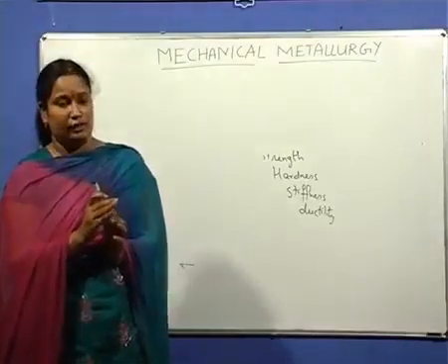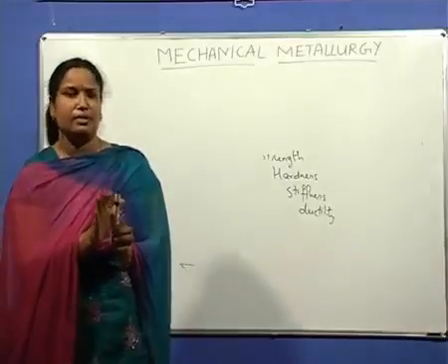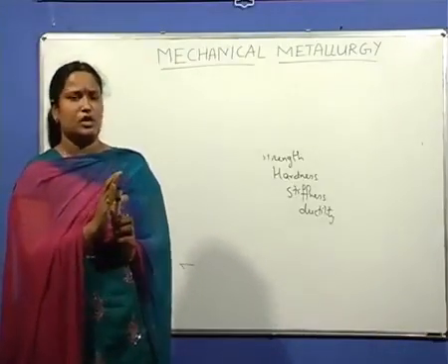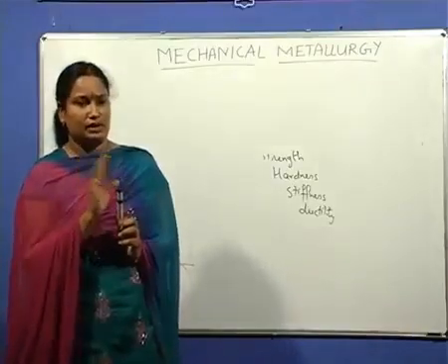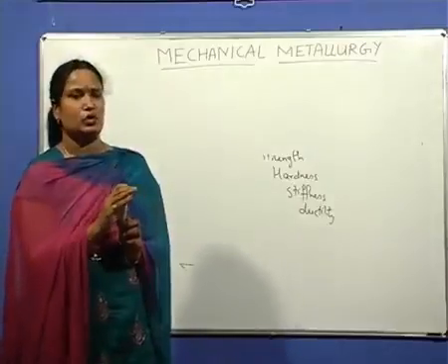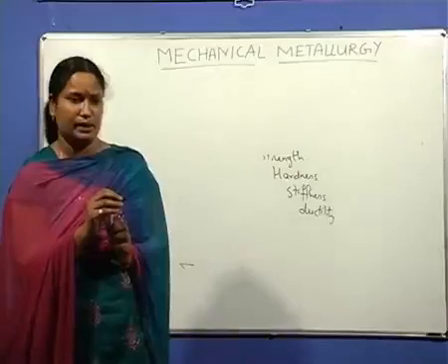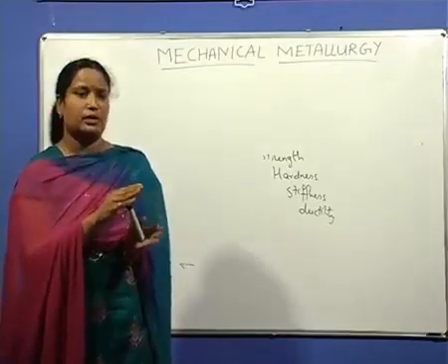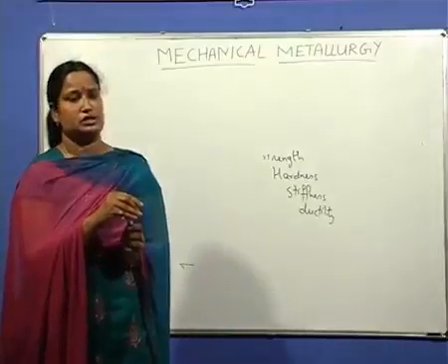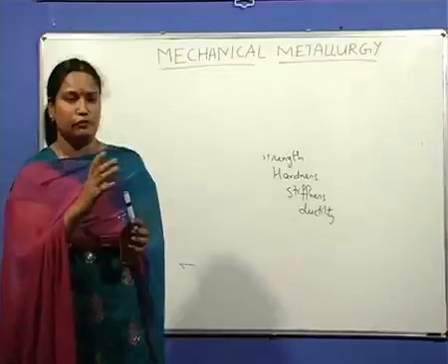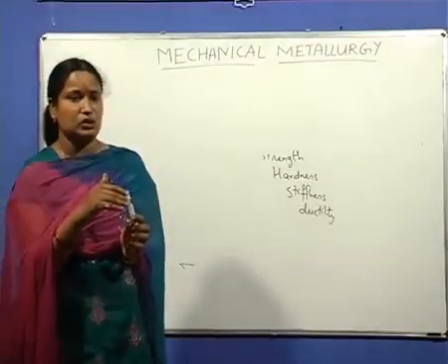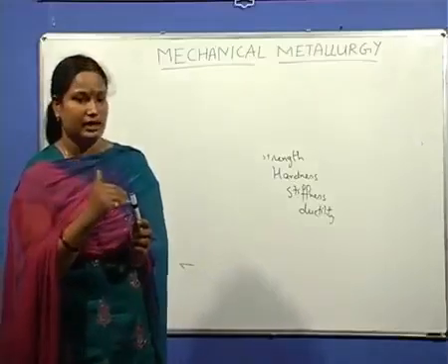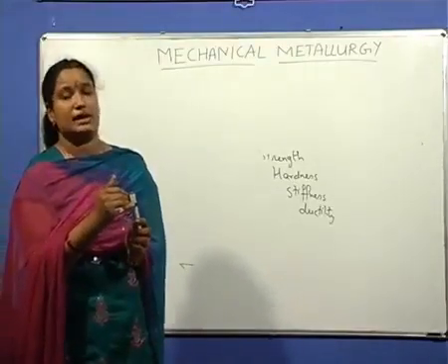The elastic deformation that we have discussed earlier is time-independent deformation, whereas viscoelastic behavior, or viscoelasticity, is seen in many polymeric materials, polymers, as well as, to a lesser extent over a certain temperature range, in some crystalline materials. That means it is time-dependent deformation. Upon the application of load, the material undergoes elastic deformation, which is not linear, and upon the removal of load, the material cannot completely regain its original shape instantaneously, but the elastic strain recovers over a period of time. The strain recovers with time, which is known as inelasticity.